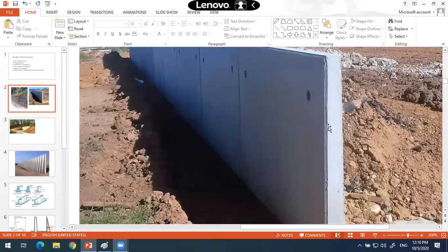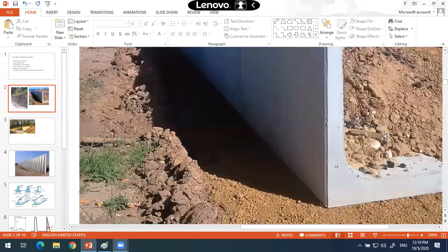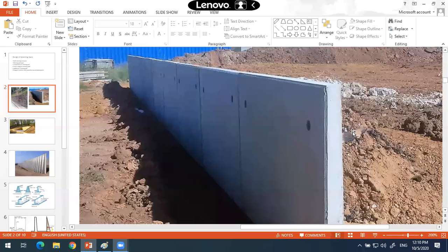But what is the force to which this retaining wall is designed? It is designed for the lateral earth pressure. So in considering the density of the backfill, it may be taken as a partially saturated soil. The density will be increased, but you should take care that it doesn't become fully saturated at any point. I cannot design it for a huge saturation which may not occur at all.